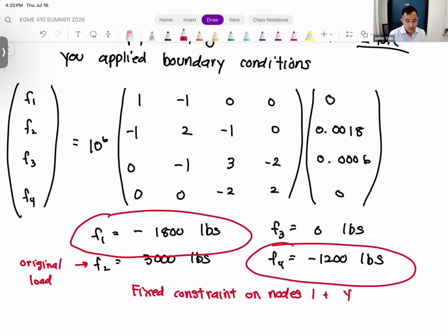Okay, 4:20, so let's get back at it. We just finished our 1D problem for trusses. You can see here it's very similar to our springs. The only difference is that our spring constant just takes one more equation to compute, it's just AE over L.